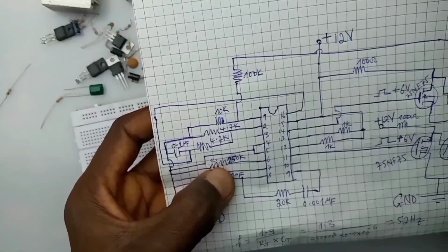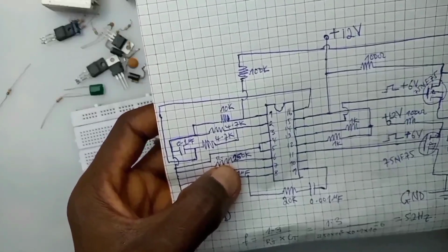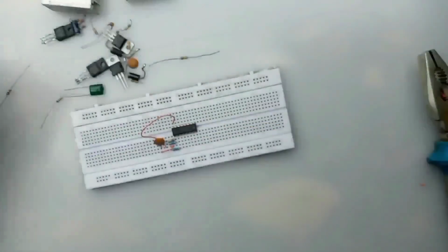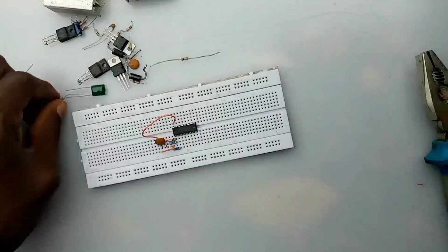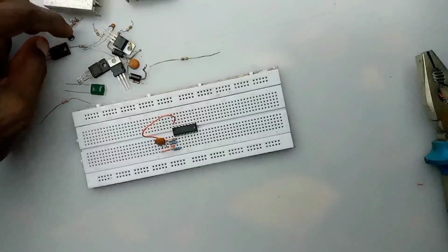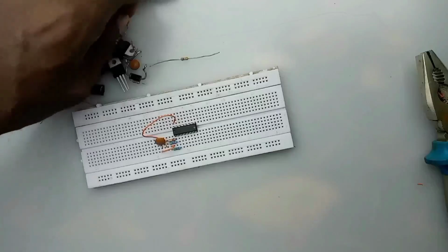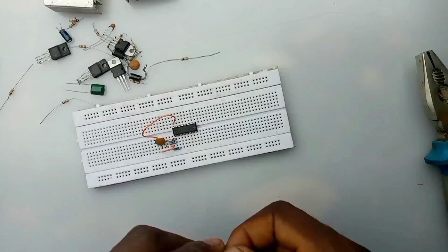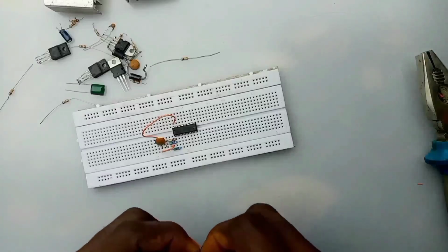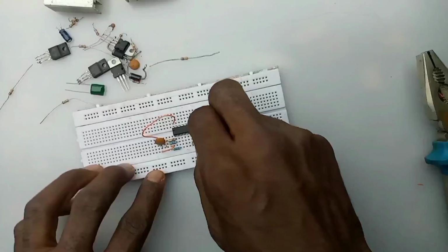Similarly, mounting our timing resistor RT, 250 kilo ohm. We shall mount two 100 kilo ohms in series and two 100 kilo ohms in parallel to have 250 kilo ohms.